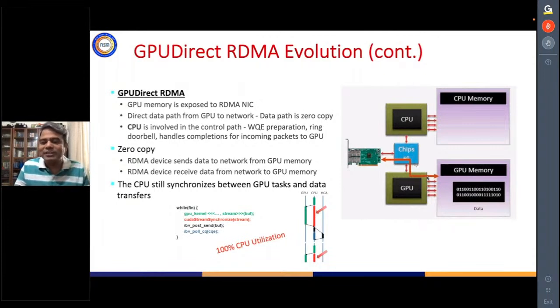But all they do is, in that packet that I showed in the previous slide, apart from the source and destination identifier address, it contains a transport header, which is nothing but a DMA pointer to the memory location of the destination where the payload needs to be put.